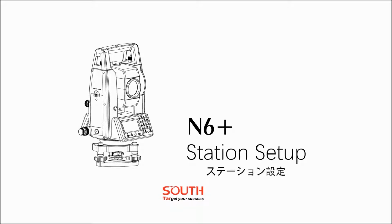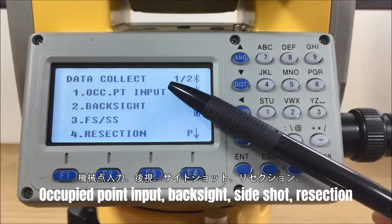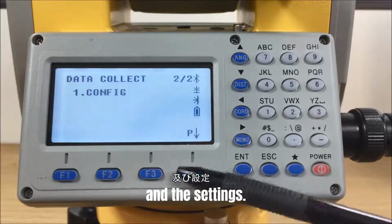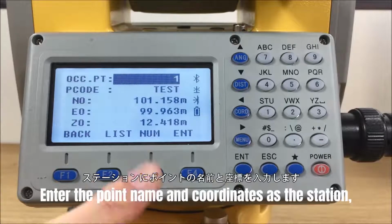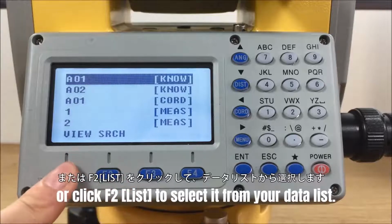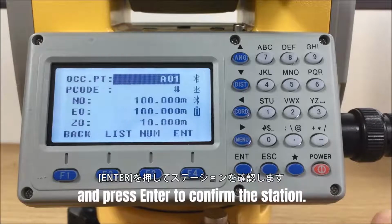Before we get started, let's have a quick look at those options under Data Collect: Occupied point input, backsite, side shot, resection and the settings. Let's click the first one, occupied point input, to set the station. Enter the point name and coordinates as the station, or click F2 list to select it from your data list. Click F1 view to check the data and press enter to confirm the station.